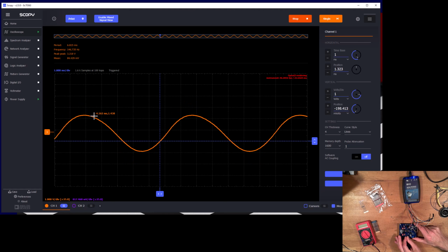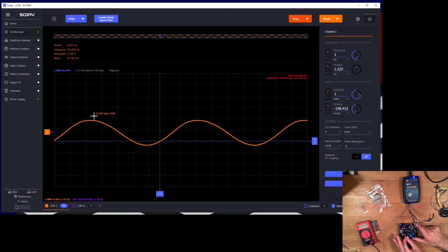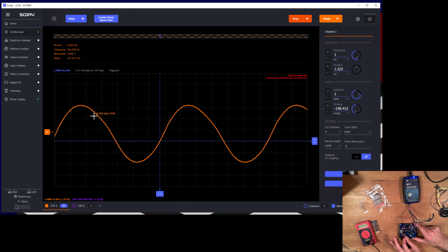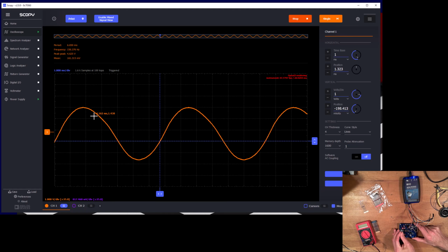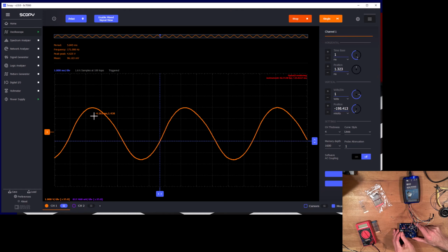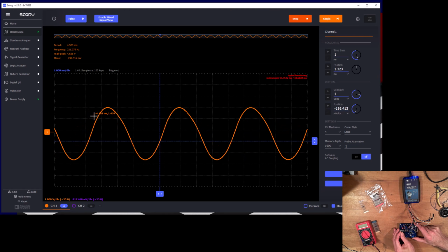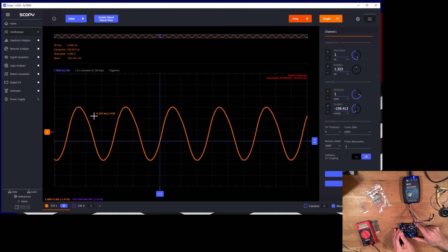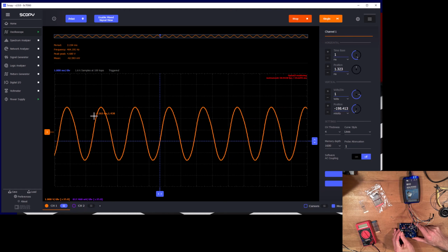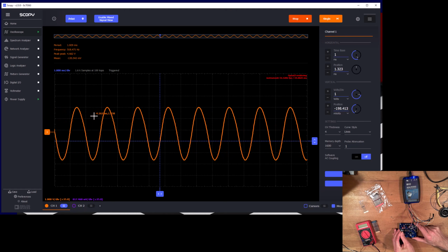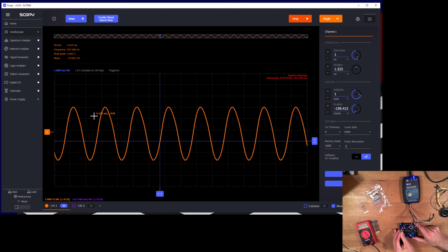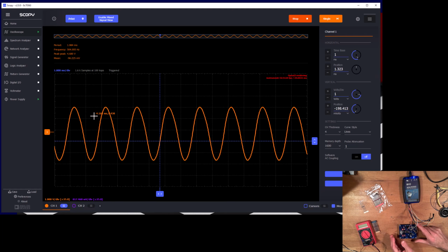Again, we've got that diode clamp in there, so we expect that at low gains where that diode is not coming into play, we should have a nice pretty sine wave, and as we increase the gain, those diodes start to kick in. Okay, let's get our frequency up to about 500 hertz, and that makes it easy to mentally calculate things like distortion, where our distortion components ought to live. So we've got a fundamental frequency of about 500 hertz.